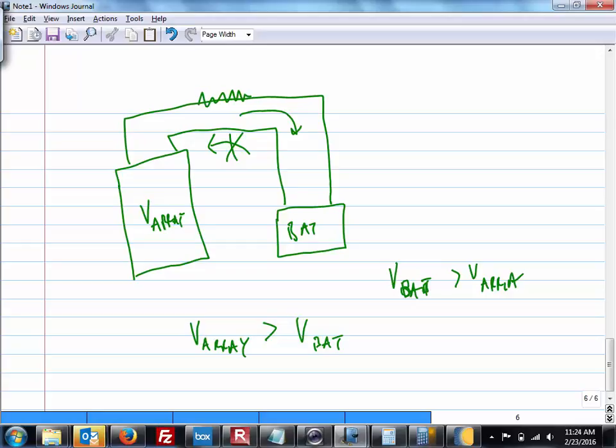Under normal operating conditions, current does not pass through the bypass diodes. However, if the cell develops an open circuit or high resistance condition because of shading or damage, bypass diodes minimize power dissipation by the shaded cells, preventing them from overheating. Nice. And there's a picture of that. That's actually figure 1119 in the textbook.